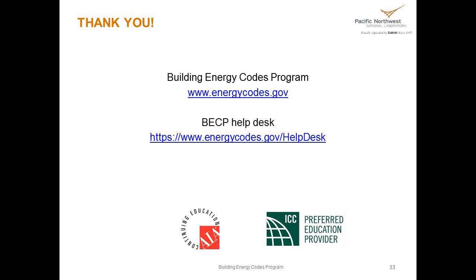As we saw in some of the requirements in the codes, skylights are not required in climate zones 6 through 8, which is basically the really cold climate zones. Climate zone 8 is Alaska. So in those climates, the trade-off simply doesn't work. You save some energy from the lights, but you're losing so much heat from the skylights that that trade-off doesn't work anymore. But generally, for side lighting and for skylights, in many parts of the continental US, it should work. It is a positive trade-off.